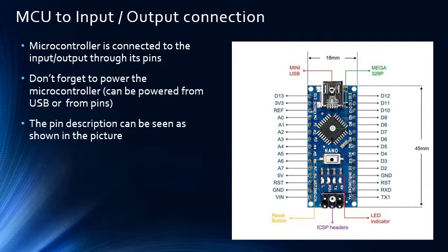You can see here there are many things. Now I'm going to cover the input pin for now. The Arduino requires some voltage, so you can apply the voltage for the power supply of this Arduino through this pin, the voltage input pin. And because there is a regulator here, you need to provide a voltage higher than 5 volts.